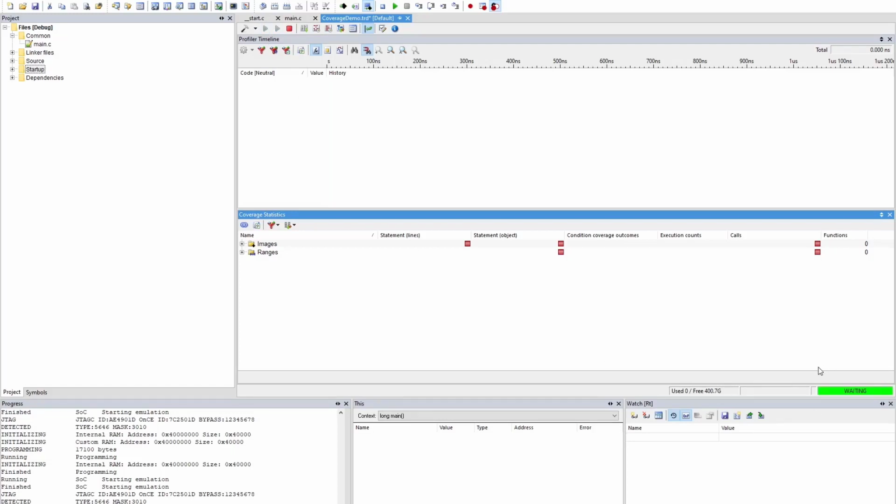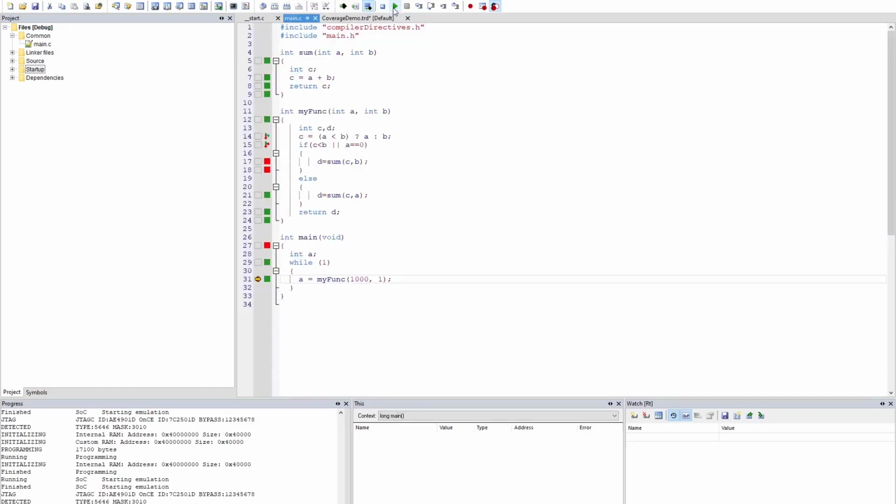And you can see that the analyzer is now in the waiting state. As soon as we run the microcontroller, the trace recording will begin, and once that is recorded, uploaded to your computer and then analyzed, you will see the coverage information. So let's continue by running the CPU. And you can already see the coverage information right here in the editor. You can see that the recording was successful. But at this moment, we will focus on our TRD file, on the trace file.